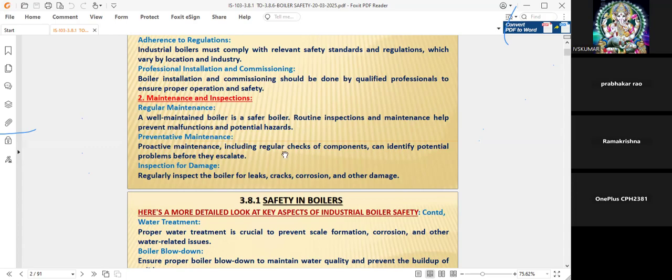It means preventive maintenance of the safety appliances like the safety valve, the boiler feed valves, and all the parts of the boiler that will be taken care of. Keep the standby ready, so whenever the situation comes, we can immediately change to the standby. But there is no regular standard like we have to stop every 6 months or every 1 month.